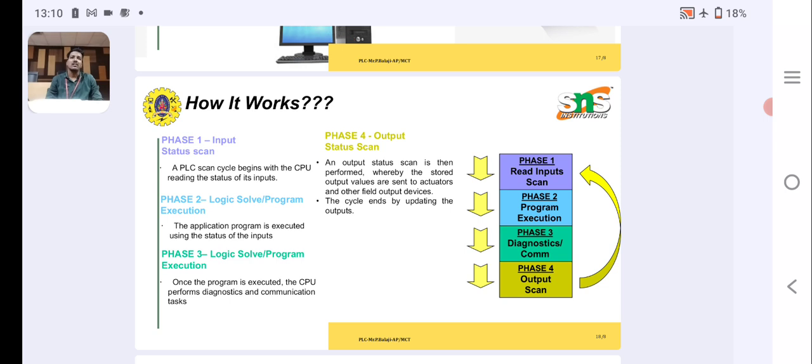At the start of each program cycle, the CPU scans all the inputs and copies the status into input output addresses in RAM. As the program executes, the stored input output data is retrieved from the RAM as the logic operations are carried out. Resulting output signals are stored in the reserved output section of RAM. At the end of each program cycle, the RAM is transferred into the appropriate output signals. The output retains its status until the next updating. This method of operation is termed mass input output copying.